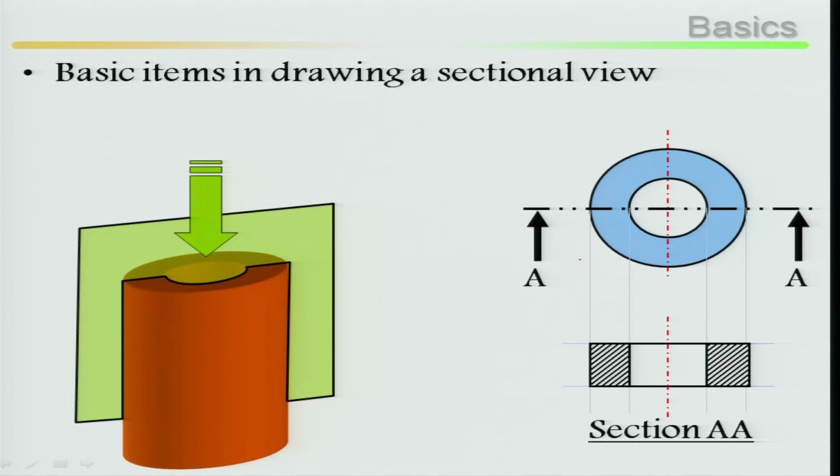Sectional view at AA. In this case what happened? Longitudinally it has been cut from the top view. This is your top view, you cut it longitudinally. Then what happened? Once you cut it, you have taken this part. If you look here, the arrow mark has again been shown, one dash, small dash, again small dash, other dash. This line shows your sectioning, arrow A at AA.